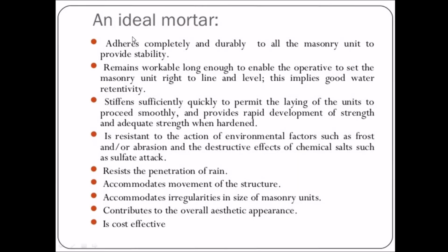An ideal mortar should adhere completely and durably to all the masonry units to provide stability, and it remains workable long enough to enable the operative to set the masonry unit right to the line and level. This implies good water retentivity. It stiffens sufficiently quickly to permit the laying of the units to proceed smoothly and provides rapid development of strength and adequate strength when hardened.